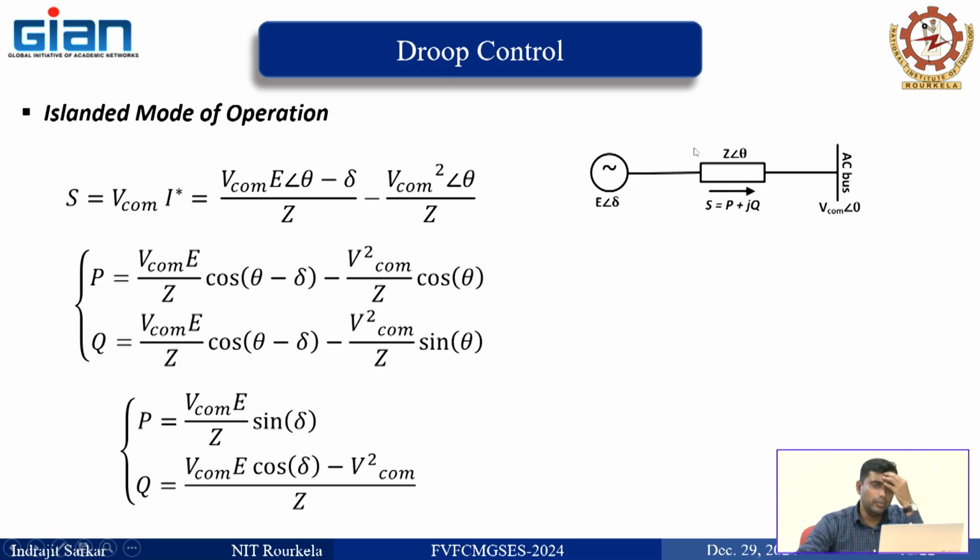Now if you don't have this impedance, you need to have it. I will tell you why. This impedance may not be there, but definitely there will be source impedances, which will also come into the picture. But dedicatedly we need to put an impedance here. Why? Because this source is not a pure AC source, it's a PWM output from a voltage source converter, right? It's a PWM output. So the voltage here is something like this.